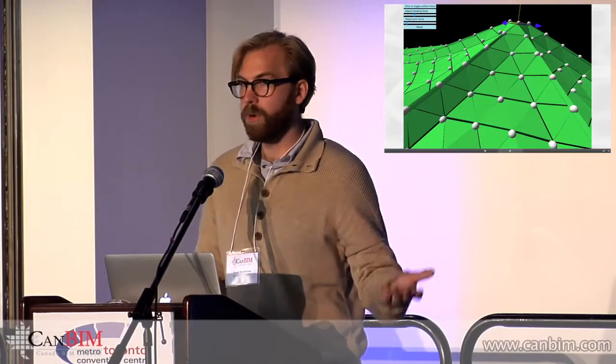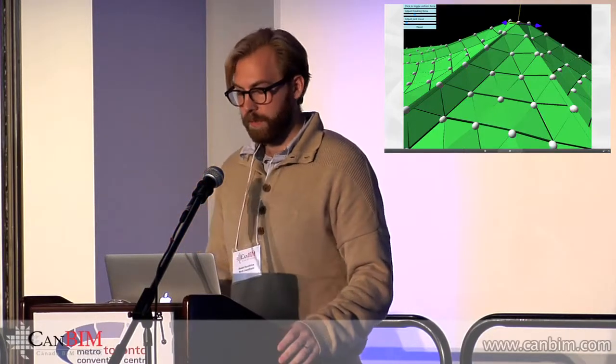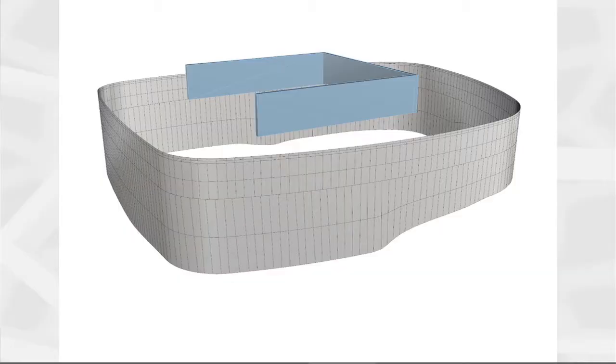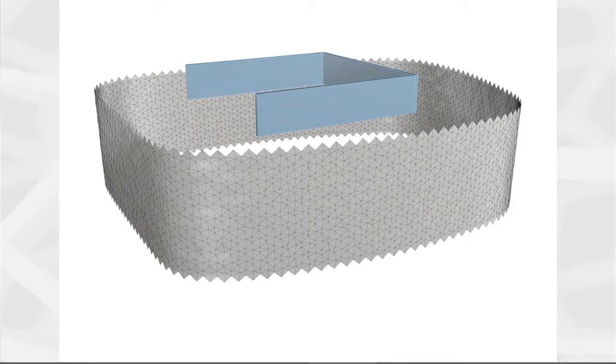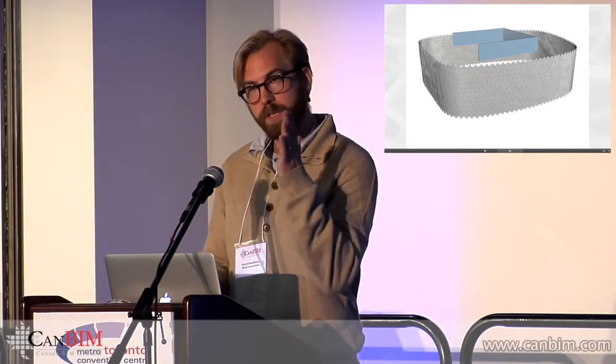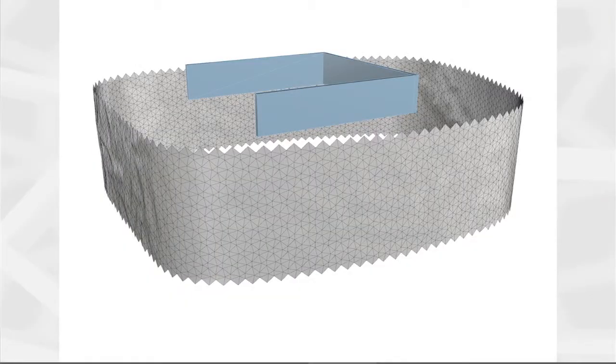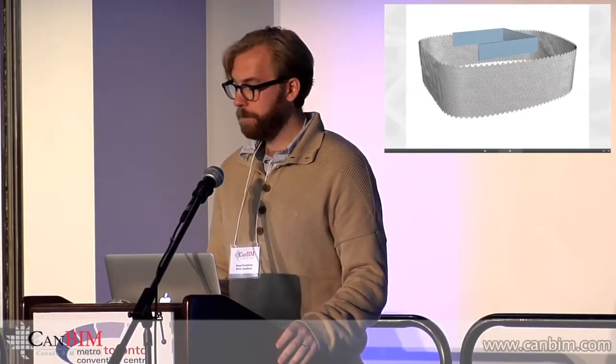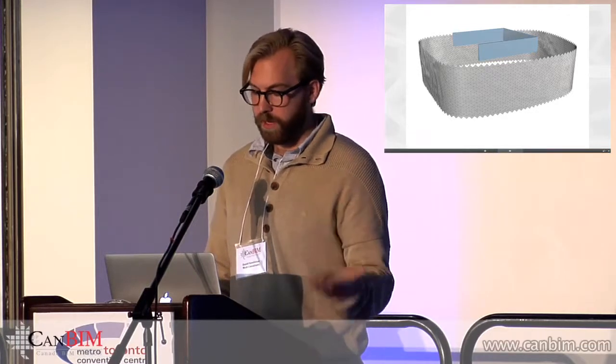So we applied a kind of grown-up version of that simulation to this project. The starting point for us is typically the smooth underlying surface, where our task was initially to map this pattern that they had defined in the plane onto the surface with all its imperfections and distortions. And it's a bit difficult to see here, which is maybe a good thing. But between this slide, where every panel is actually unique because of this distortion, and this slide, although there's some folding similar to what you just saw, but to a much lesser extent, you can maybe see it over here, each panel is one of 3 types. So there's 7,000 panels here, and you can mass produce 3 types, and every one will fall into one of these 3 types. Of course, this doesn't adhere to the boundary condition, which is always an issue.